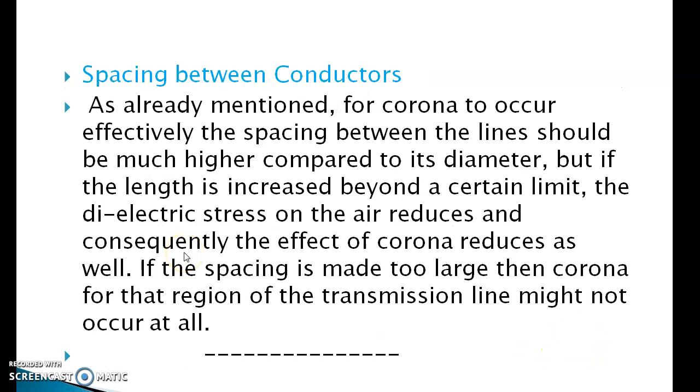Spacing between the conductors. As already mentioned, for corona to occur effectively, the spacing between the lines should be much higher compared to the diameter. But if the spacing is increased beyond a certain limit, the dielectric stress on the air reduces, and consequently the effect of corona reduces as well. If the spacing is made too large, then corona for that region of the transmission line might not occur at all.